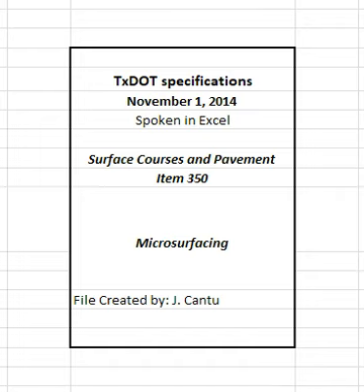Sieve size number 50 with 10.0 to 25% passing. Sieve size number 100 with 7.0 to 18% passing. Sieve size number 200 with 5.0 to 15% passing. Table 2. Aggregate quality requirements. See table in specifications. 1. Surface aggregate classification of A is required unless otherwise shown on the plans. 2. Only applies to crushed gravel.